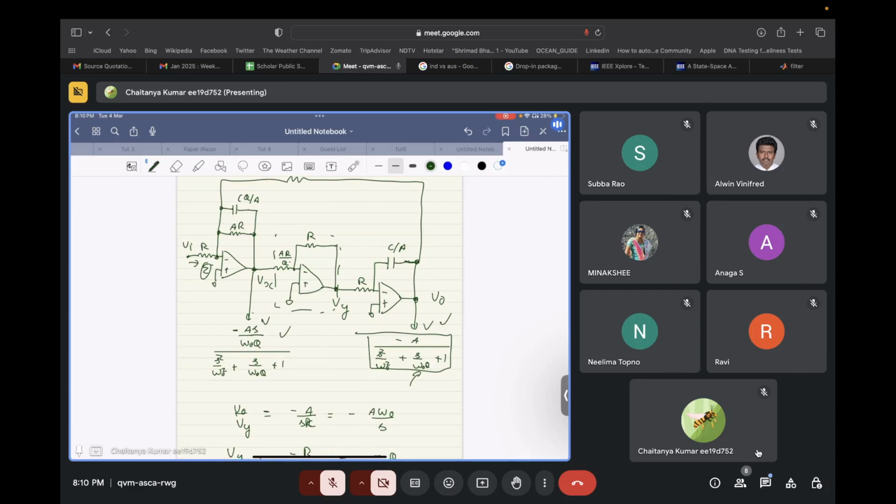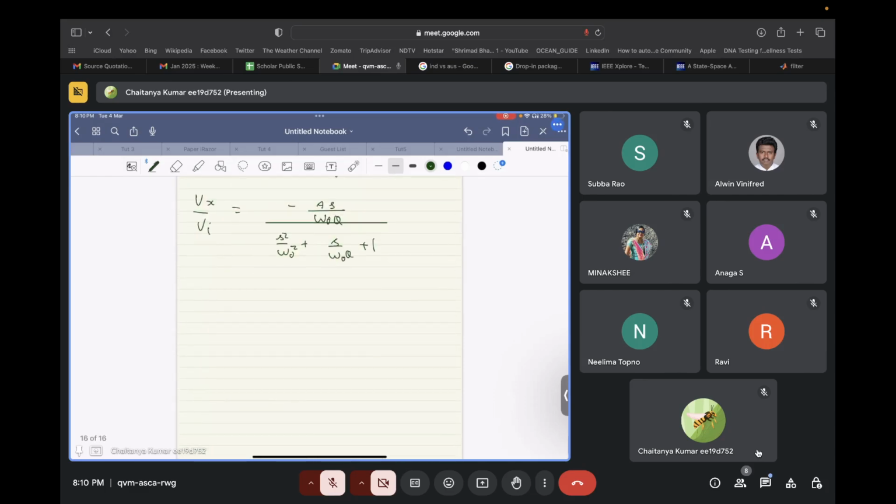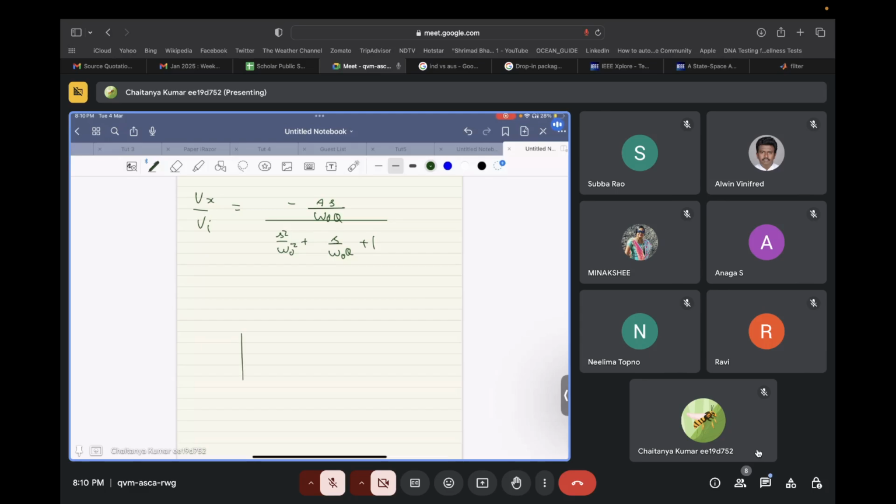Okay, so whatever technique we applied in order to scale the voltage at the output node, or the voltage at this band pass node, is called dynamic range scaling. So it can be done at the output of any op amp. So how it works is as follows. Let's say in a very big network with multiple op amps, you have an op amp which has an impedance over here. Let's call this ZF, and it loads some other impedance. Let's call this ZL. Some current I1 is coming into the virtual ground of this op amp, and some I2 current is leaving, and there is a very big circuit around it.